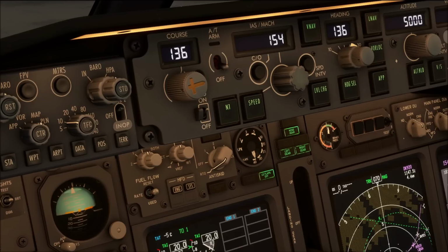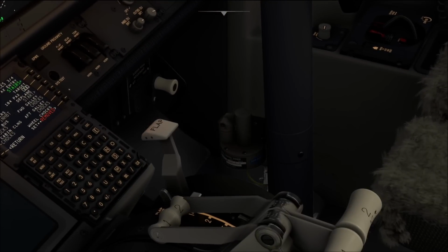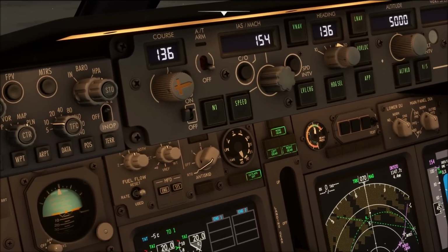On the ground during icing conditions this is different. So now they've reached the 40 position. Let's put them back in the up. So on the ground this is different. On the ground, if the flaps ever stop at a certain position, then you would immediately select the flap lever to the associated position in order to avoid damage from occurring to the flaps and the flap motors. So there is a different logic that applies between ground operations and flight operations.